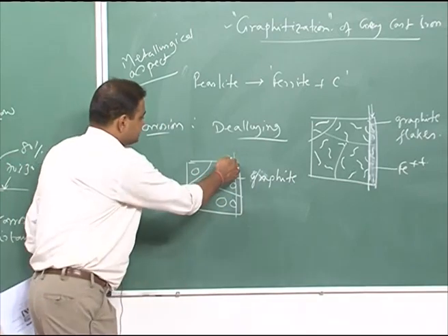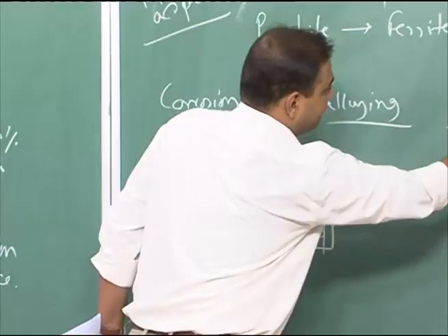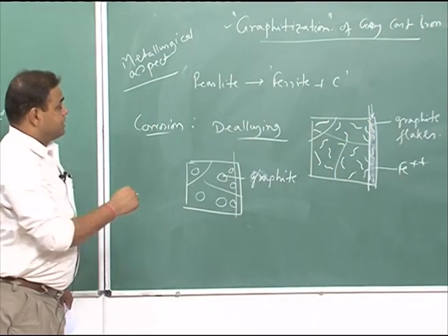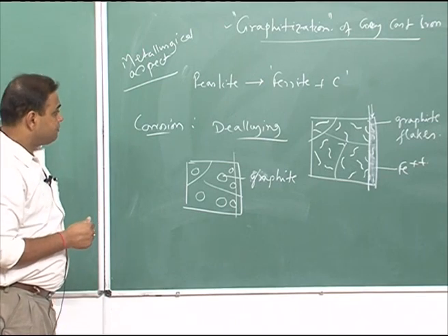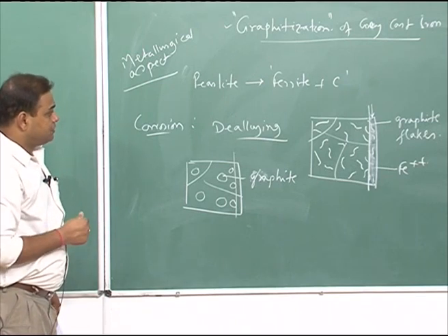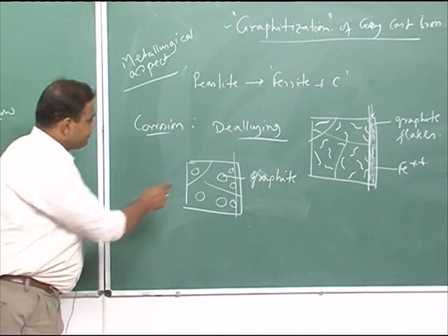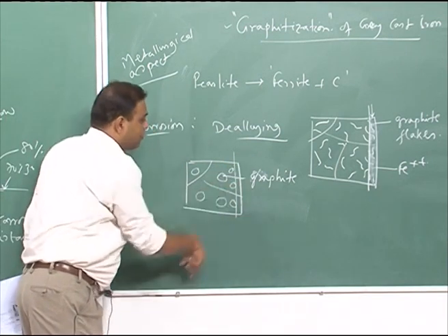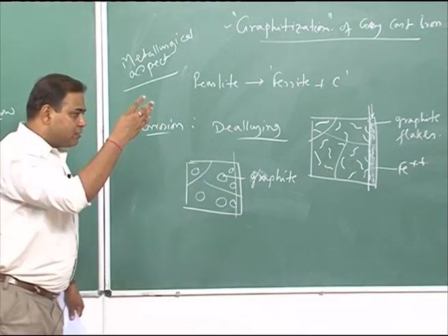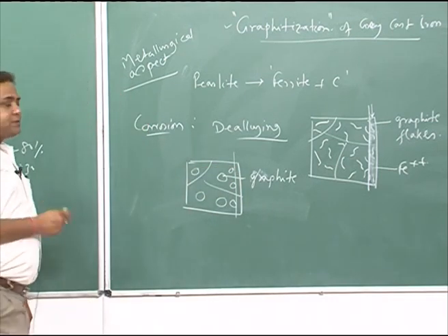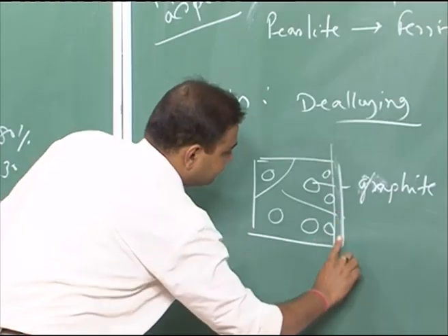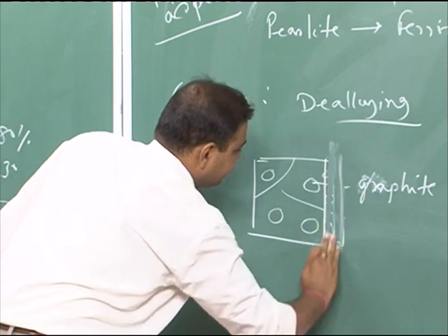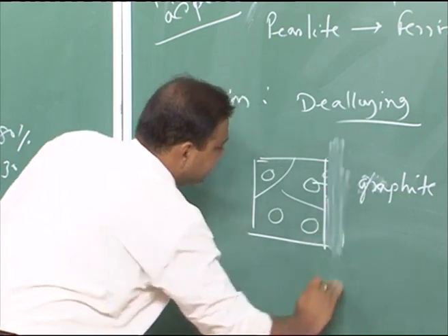The surface would not have the nature that is possible in graphitization of grey cast iron, because of the network formation by the graphite flakes. Since the nodules cannot hold the residue, it will fall off and the system will decrease its dimension, but the actual surface would always show that graphitization dissolution has taken place.